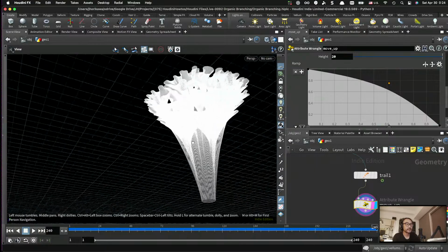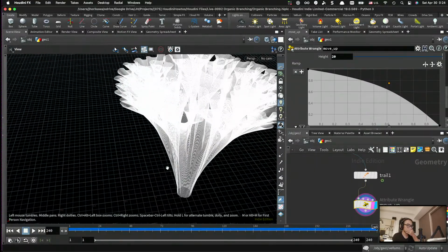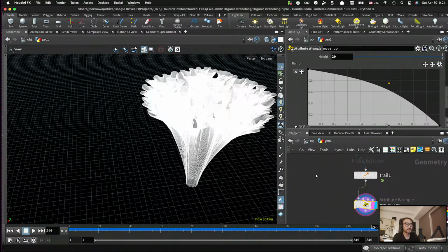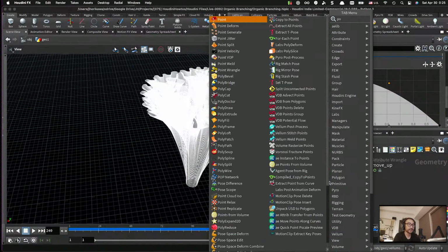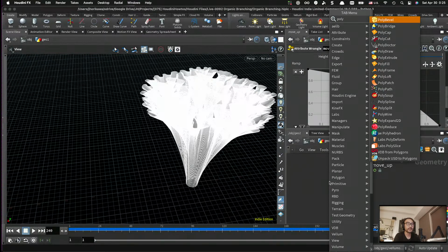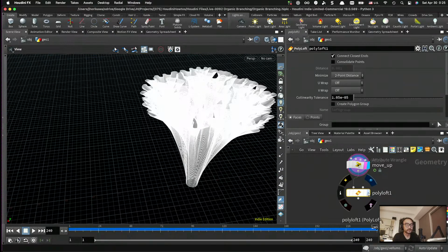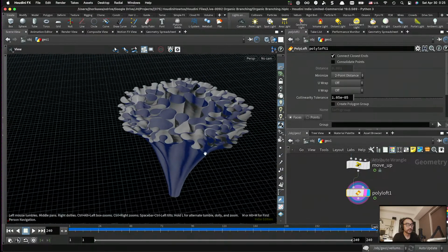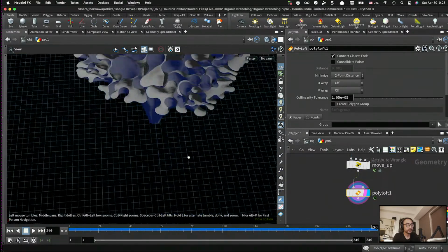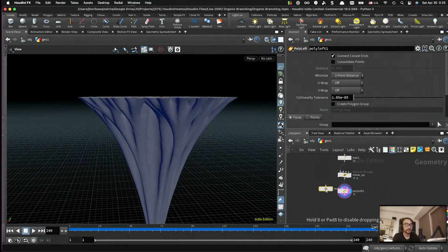Just like that. Okay, so right now this is just a contour, so let's connect these curves together to create the geometry, and that is also easy. You can just use polyframe, poly loft. And that's it. And maybe I can use a reverse.